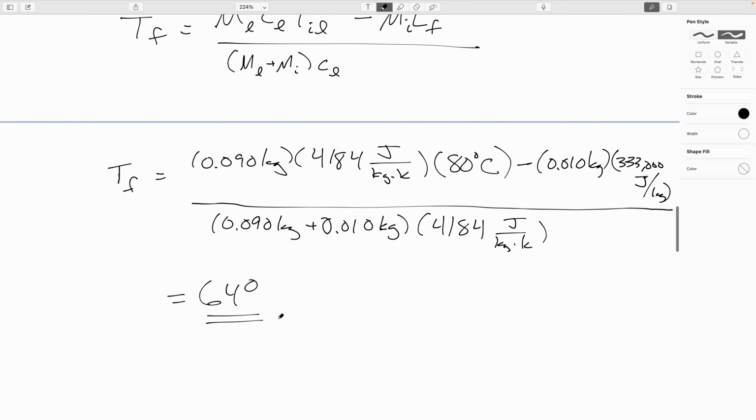If the final temperature is either above the initial temperature of the hot thing or below the initial temperature of the cold thing, that means you did not completely change the phase of the thing, and then you have to go back and revisit it. Or if you're just being asked for what the final temperature is, the answer is the temperature of the phase that you're stuck in.